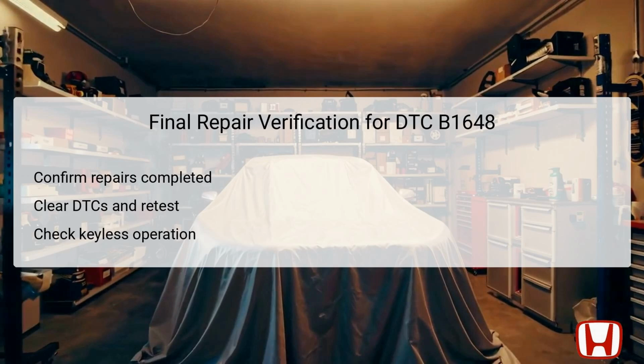After addressing the DTC B1648 by following the troubleshooting steps, it is important to conduct a final verification of the repair work. Start by confirming that all repairs or part replacements have been completed thoroughly. Clear any remaining diagnostic trouble codes using the HDS to ensure a fresh diagnostic environment. Following this, retest the keyless entry system's operations to confirm that the issue has been resolved.